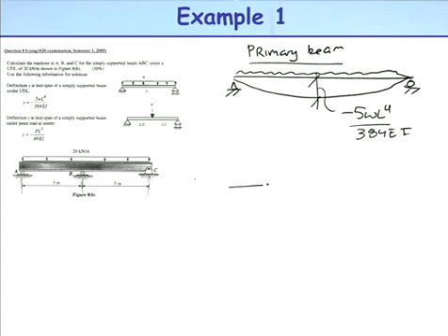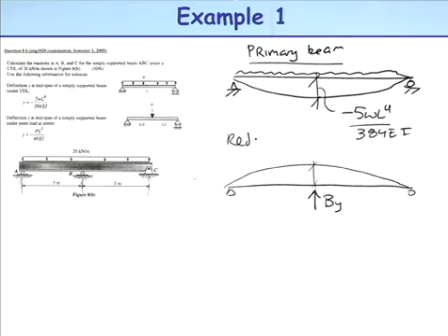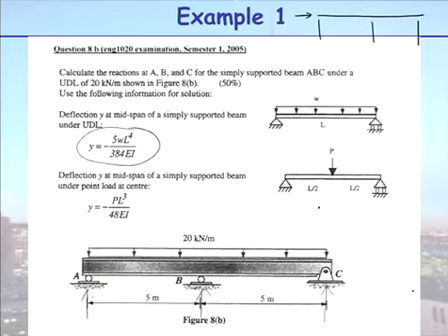And we can't go just taking supports away, so we then are going to put it back as if it's a load. And then we need to know what this deflection here is. So this is our redundant system, where we're putting back what we took away. So we have a force By, and I've drawn it small here, but going back here, the second formula you were given was the deflection in the middle of a simply supported beam.